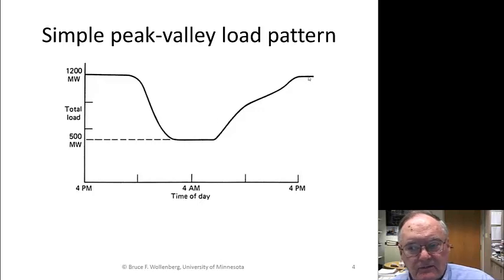The highs are different for different days of the week. We'll see this at a slide near the very end of the second series on unit commitment. But typically the load is going, and this is because during the day people are up, they're running things in their house, businesses are operating. Then at night people go home, the business is shut down, turn the lights off, turn the machinery off, and eventually people turn their lights out, and we reach a certain load during the night.